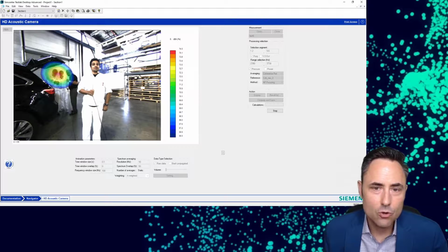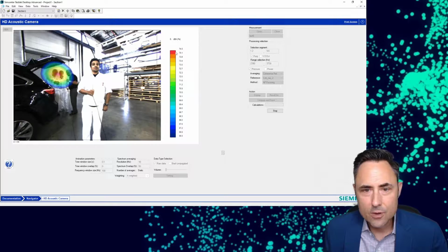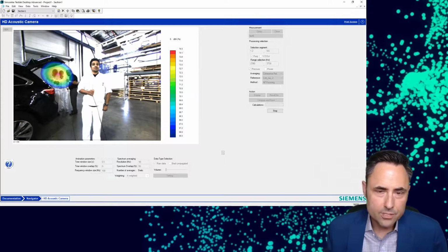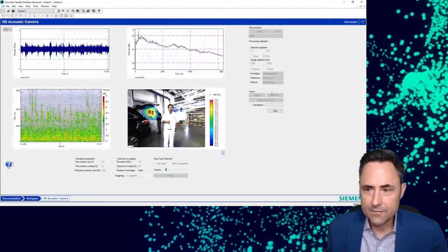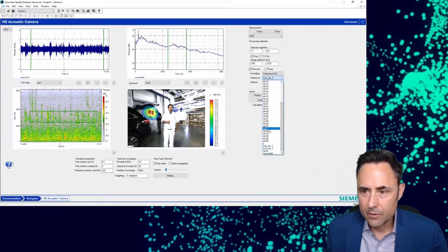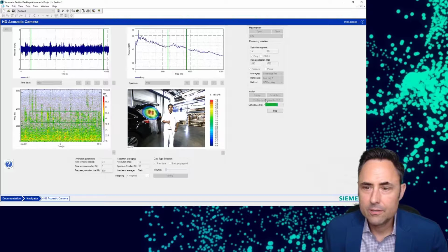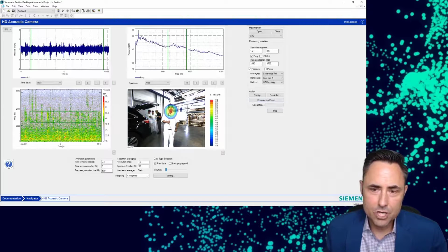So this guy's not correlated with that transducer like this sound source is. And so I can see 74.5 decibels of sound pressure is responsible from these guys back here. Okay, whereas if I go to coherent mic 1 and I show you that result, boom, I can see how much of the contribution he's responsible for, and this sound source disappears.